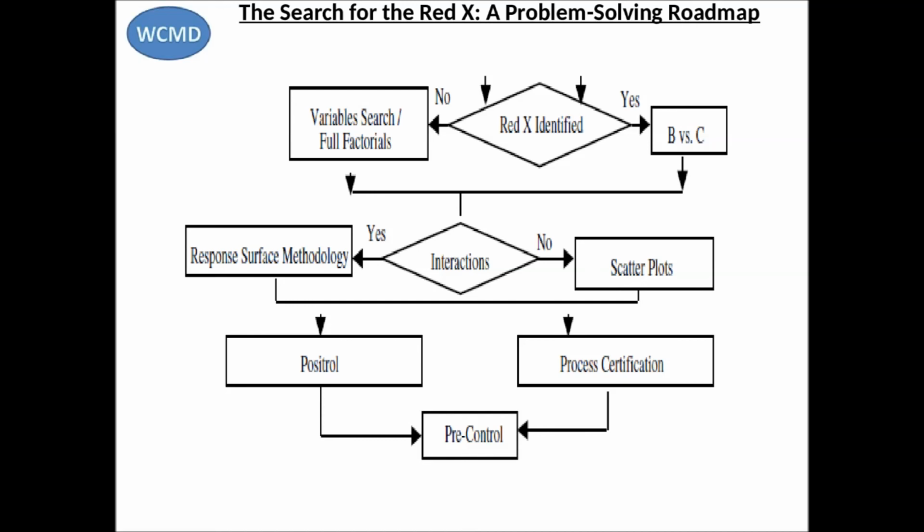But all of this work comes to naught if these important variables and their tolerances are not controlled in day-to-day production. Locked up, frozen. We have seen scores of companies where good DOE work resulted in drastically reduced defect levels, only to find in subsequent production that the defects crept back in again. Then a procedural plan must be established to ensure that important variables that were characterized and optimized through previous DOE experiments are kept under tight control with a who, how, where and when plan.